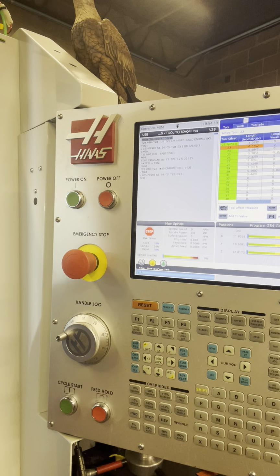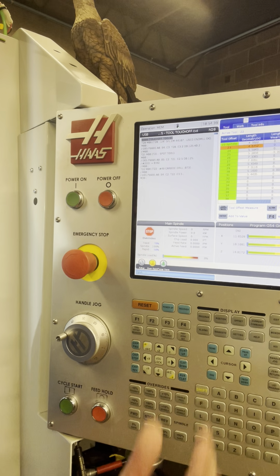Okay. We have some. One of ours, we lasered on it actually. It's 108 thousandths from the virtual sharp to where the actual tool is. So that one will scrap a part. So I'll put 130 thousandths in instead of 20. But I know that, so when we run that job again, it's automatically in there.